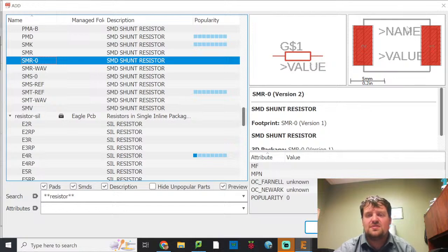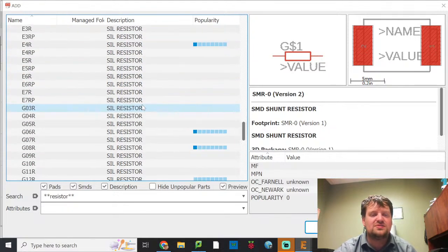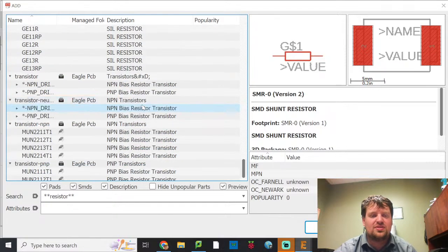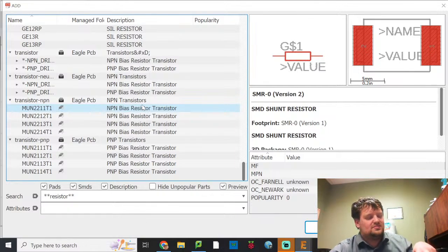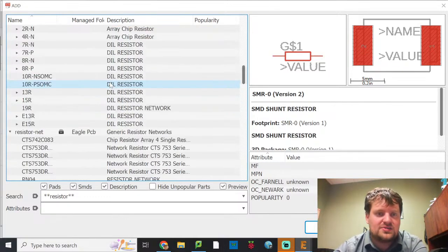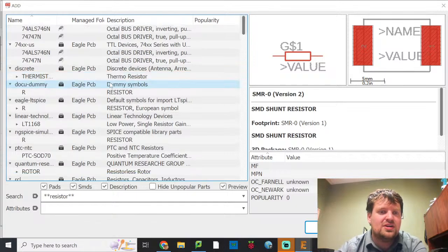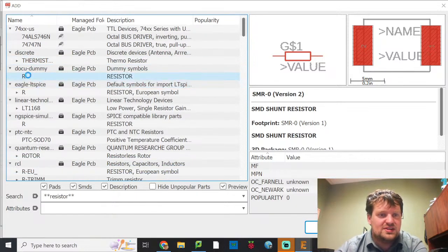Surface mount components tend to be a little bit more difficult to work with than through-hole resistors. Through-hole resistors are the ones that have two metallic leads that you shove into a circuit board and then you solder the bottom side. What I would suggest is that without having a reflow oven here at Doan, it's just best to do through-hole components right now. So we're going to be looking specifically for through-hole resistors.